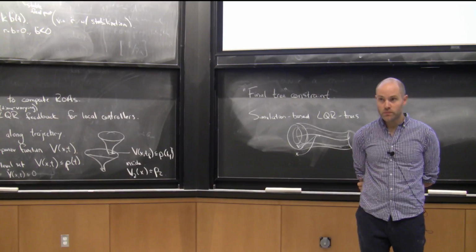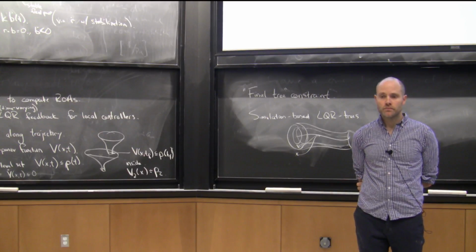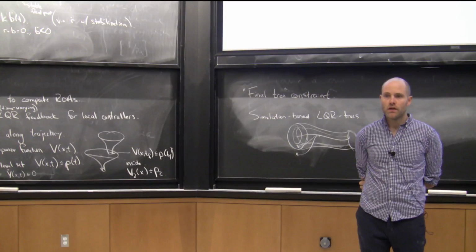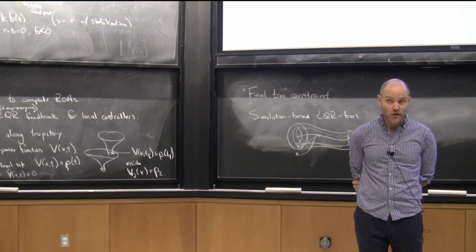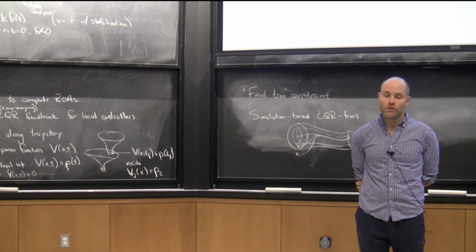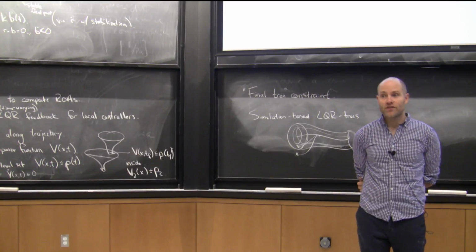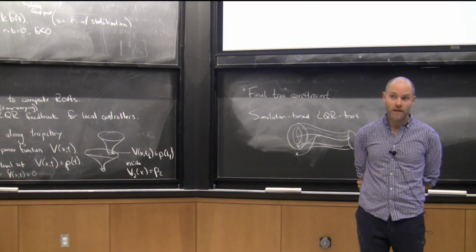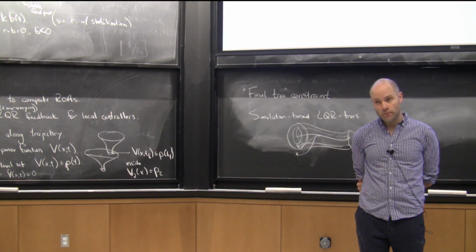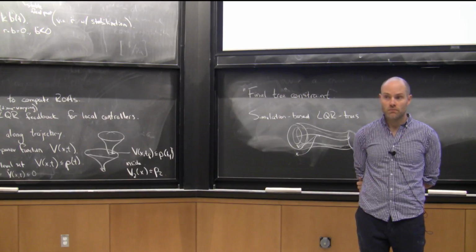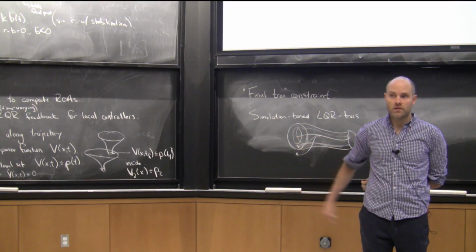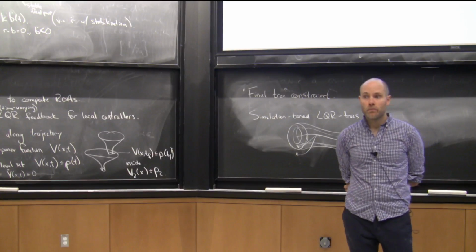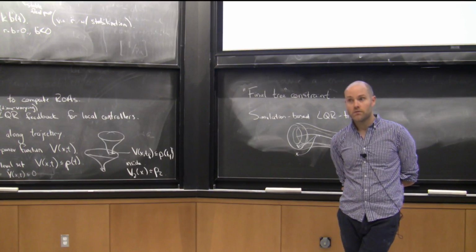Yes, I think that is within scope. If the pose comes out, but it could be one of 3 different geometries, for instance, then you could ask for a common Lyapunov function that works for all 3 of those. If you had a pre-computed library of maneuvers, you could ask which of them is going to work for all, given my current uncertainty. There are probabilistic versions of the sums of squares that give you some chance constraints. The more of these things you add on, the harder it gets to efficiently solve with sums of squares. But I think those types of uncertainties are within bounds.